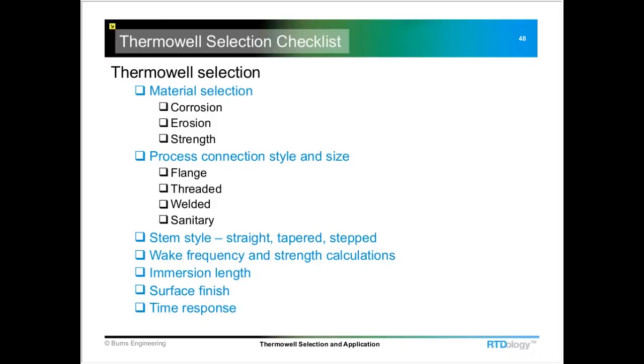It's already defined. But then when we get down to the wake frequency and the immersion length, and then picking the surface finish and the time response, those are the things where the most thought has to go into it. And don't be reluctant to reach out for some help from the temperature assembly manufacturer in selecting that, because there is a pretty delicate balance between that wake frequency and the immersion length to get a good, accurate measurement that is going to have the time response required for your application.